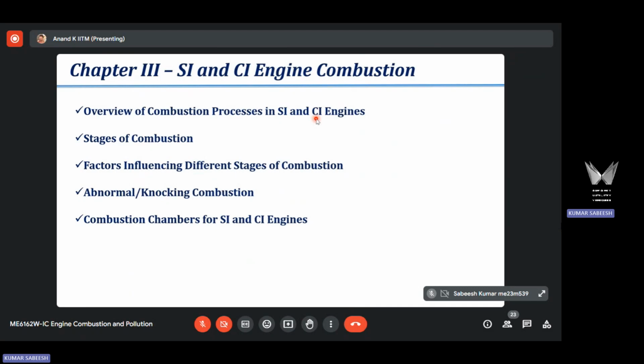And what we have in the cylinder is compressed air. So compressed air is the source for igniting the fuel, and of course fuel and air have to be mixed in the ignitable range. Combustion, as I said, cannot be initiated if you don't have an ignitable mixture, if you don't have ignition temperature. A proper combination of ignitable mixture and ignition temperature is required. Maintaining a high compression ratio, it's almost twice compared to SI engine. In CI engine, we maintain 2 times higher compression ratio. So maintaining high compression ratio is important from the perspective of igniting the fuel as soon as we inject.